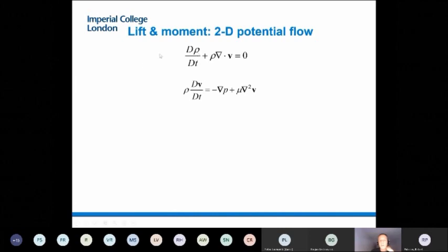Basically goes the total derivative move with the gradient of the velocities. That's fundamentally the dependency you see there. We have the second equation, which basically gives you the conservation of momentum around the flow. And basically this is Newton's law applied to flows. What it says is that the mass times acceleration, that's the first equation, is driven by the pressure gradient of the pressures that appear. There's a pressure gradient and the viscous terms.